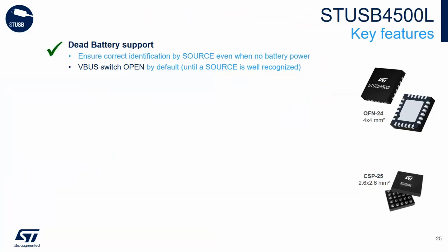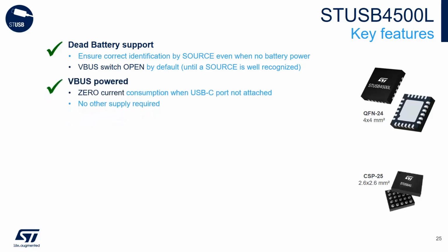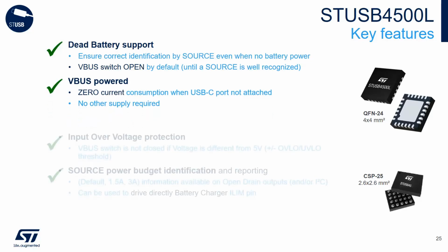In short, here are the features supported. Dead battery support. That means no battery or microcontroller is required to run the ST-USB 4500L. It provides safe and ultra-fast power-up. It is powered directly from VBus, so there's zero leakage at all on the application battery, and that extends the battery lifetime of the device.